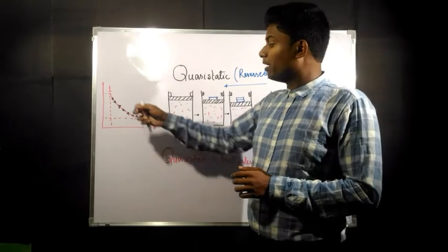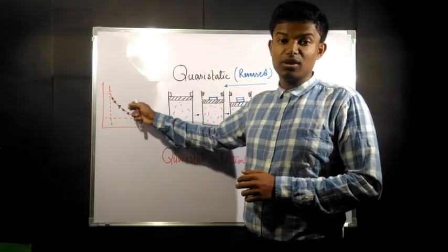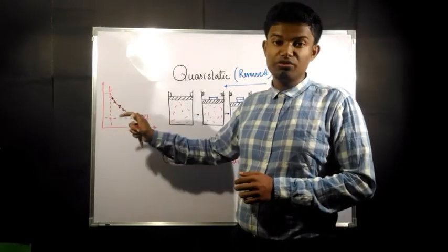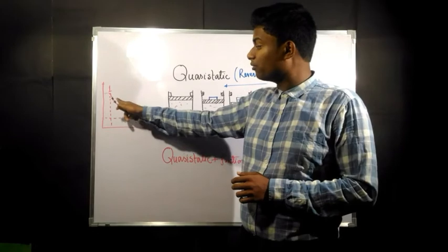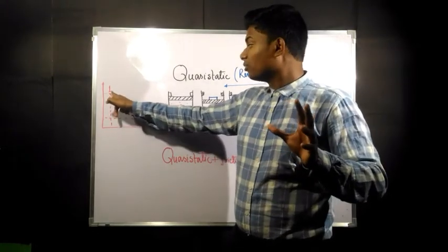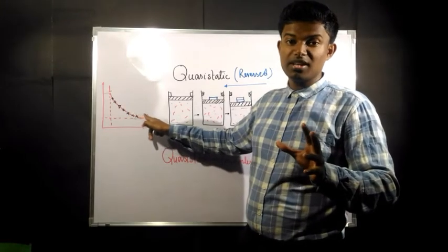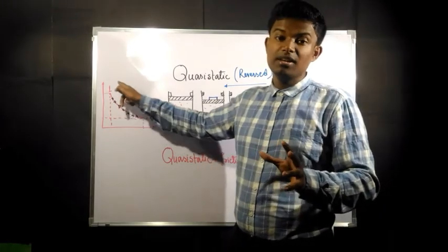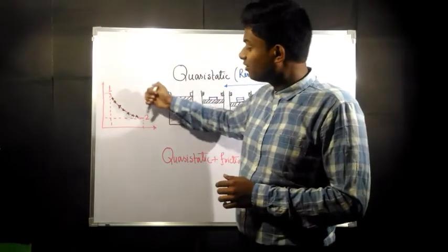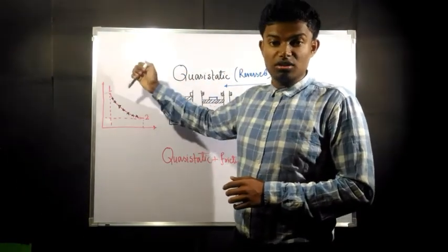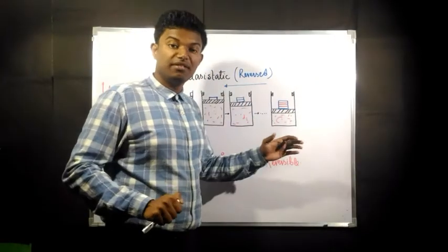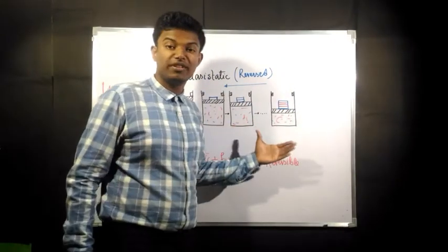So maybe we can call this reversible, but there is a condition. To be reversible, it must be frictionless, because due to friction energy is lost both the time from state 1 to state 2 or state 2 to state 1. It's not like that from state 1 to state 2 due to friction some energy is lost, so while going back due to this friction this energy will be gained back. It's not like that. In both the cases friction will be lost. For friction some energy will be lost. So to be reversible these processes have to be frictionless.